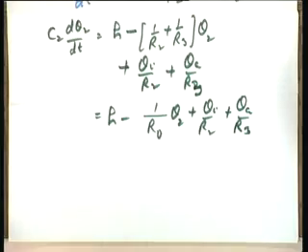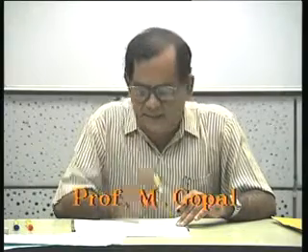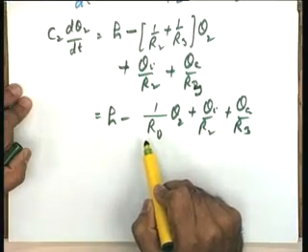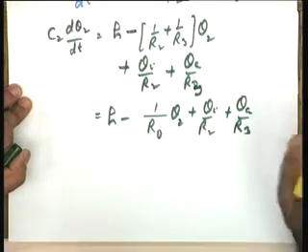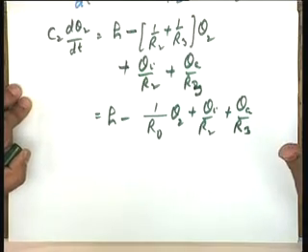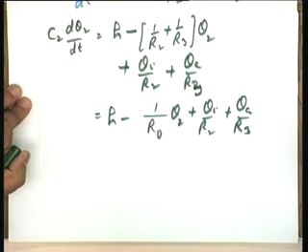You see that in an electrical circuit, resistance into capacitance is the time constant and its unit is always seconds. Now, in thermal systems, identically, a little exercise for you: look at the units of thermal capacitance and the units of thermal resistance. You will find that the units of capacitance into resistance will turn out to be seconds, and therefore, equivalent to electrical systems, C into R will turn out to be in seconds, and I will call it the time constant of the thermal system.